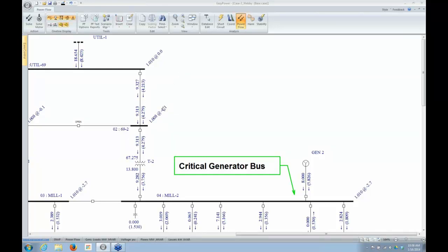Another question, is there a way to calculate power factor losses? Well, we can calculate power factor, and we can calculate the VAR losses. If you're looking for calculating the power factor penalty that a particular utility charges, we don't build that into the program because there's 1,000,000 different ways that you're billed for power factor. So you can certainly compute the power factor at any particular point in the system. So we can display this value at the interface as VARs or as power factor.